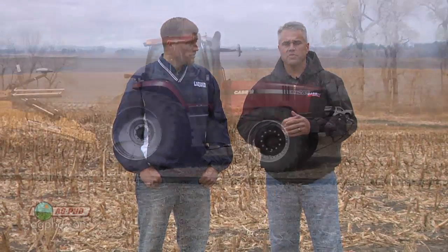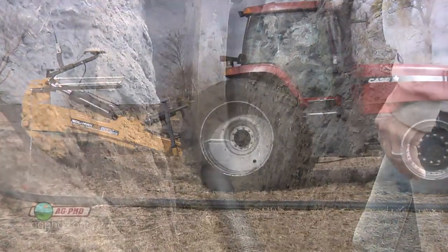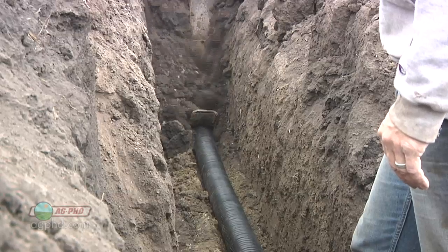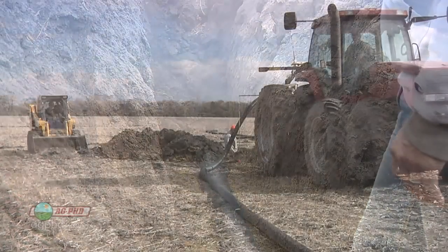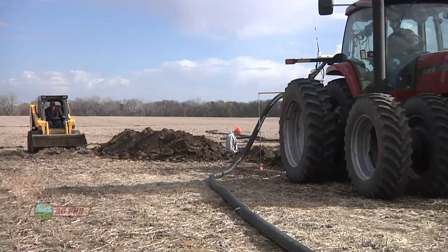Didn't even start running. That's right, because the only way that tile lines run is if the water table, the groundwater table, is above the level of the tile line. So for example, out in fields, we commonly put in the drain tile at 3 feet deep. We do that because we just want to have roughly 2.5 to 3 feet of good area for roots to grow. That's really about all we need to raise a great crop. Okay, so we put the tile lines in at 3 feet deep. As long as the water table is below 3 feet, then the tile lines never run.